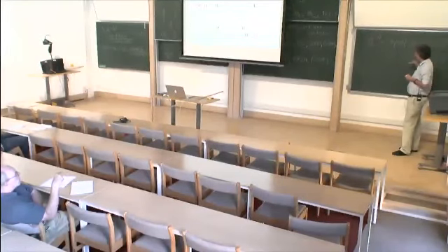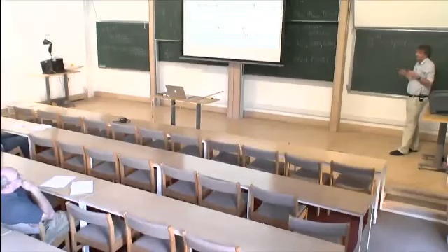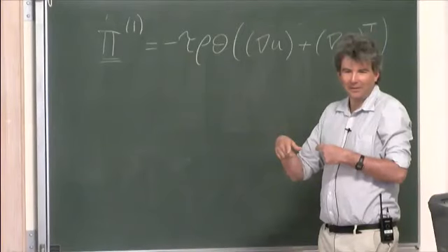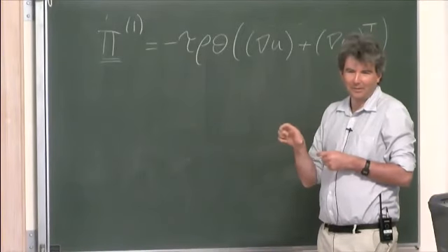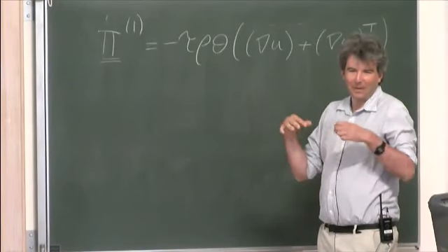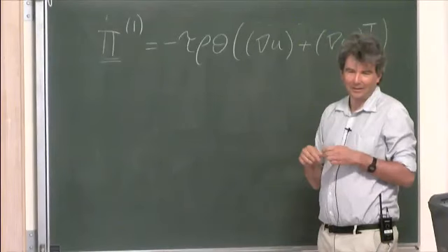All the spatial scales, because the old relationship between the collision time or the mean free path and the grid spacing, which you used to have in a lattice gas, has been removed. So you can take the tau much less than delta t, or you can make your mean free path much less than the grid spacing. So you can still be in a Navier-Stokes regime even down at the grid scale.